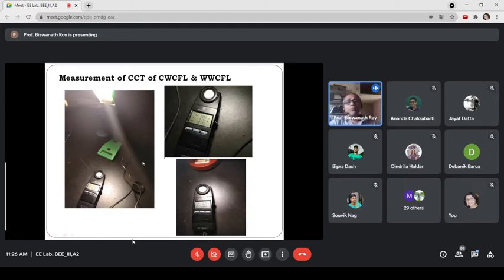I forgot to tell you how the zero error of this instrument is obtained. You see there is a cap here. This cap is used to protect this sensor. This sensor is like our eye, it needs some protection. Just as no light enters when we close our eyes, if we place this cap over the sensor and press it slightly to ensure no light is getting into it, under this condition we need to switch on the instrument. There is a switch here.